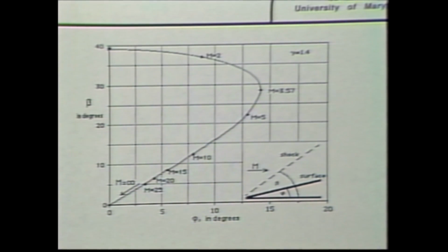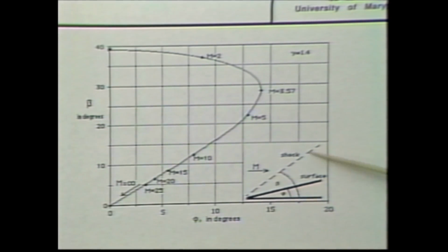What does that say? Well, if I have a vehicle that's flying through a range of Mach numbers, I have no hope of being able to match the shock to the cowl if I have varying flight conditions. Right? Angle of attack is going to change those conditions, and the engine must be designed to accommodate that.